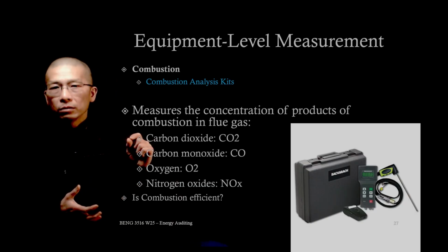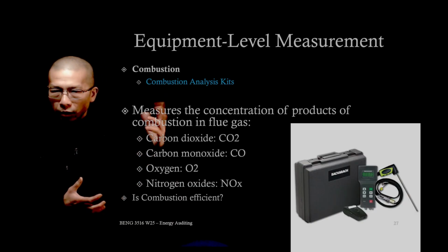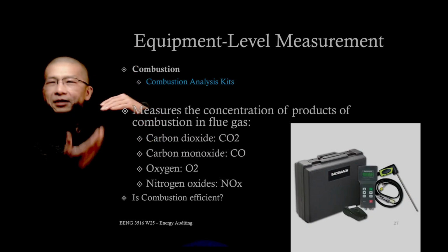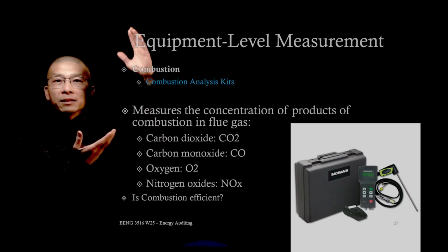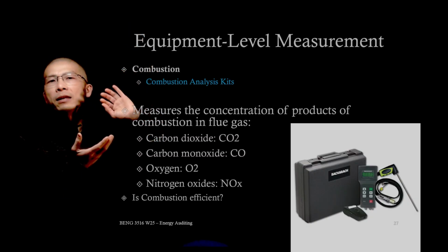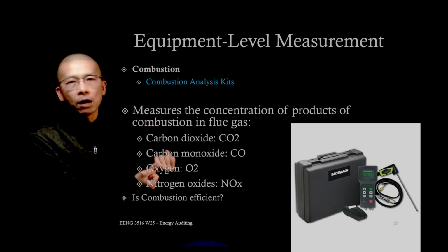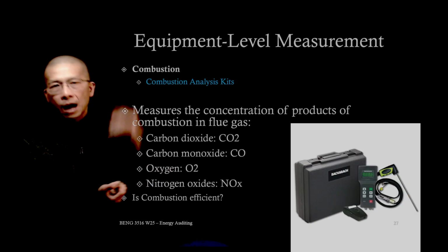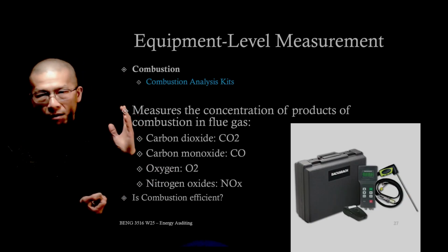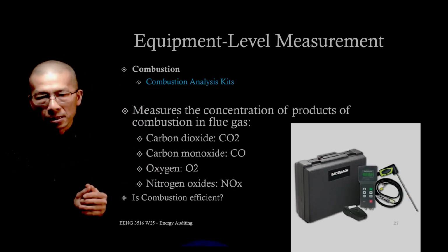Stack temperature is also measured, right? We want to know the temperature of the flue gas, because if it's very high, can we do anything to reduce that temperature, meaning taking the energy out of it before the hot flue gas goes out of the exhaust into the environment.